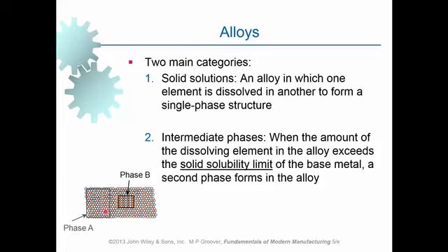As long as the crystal structure is the crystal structure of the base metal, we are dealing with a solid solution. There are some impurity atoms in it, however, properties are still a function of the crystal structure, say the crystal structure of the base metal. So this is the dominant crystal structure, and this will affect the resultant properties significantly, despite the fact that solute atoms will change the properties to some extent.